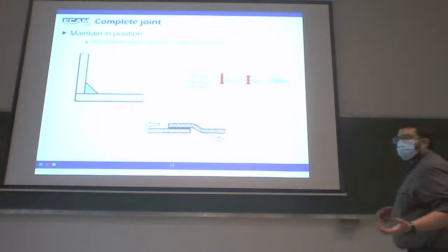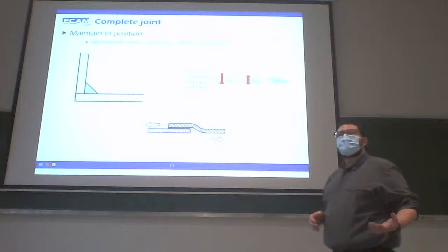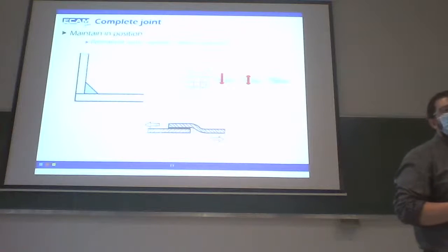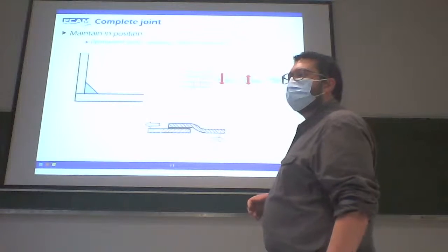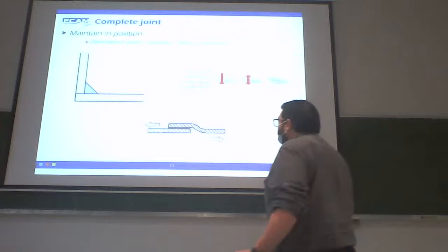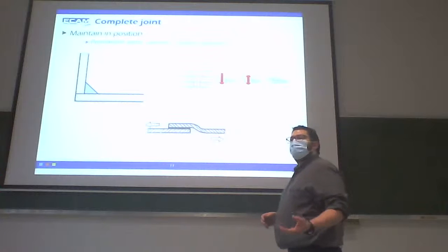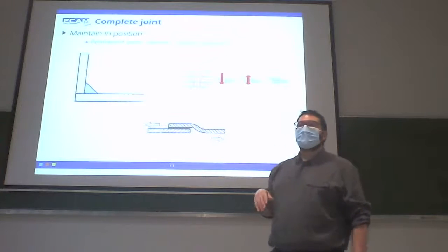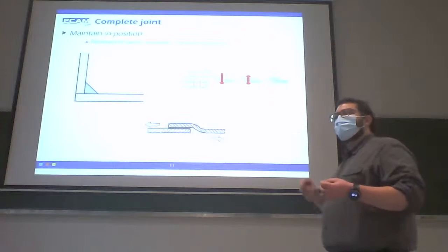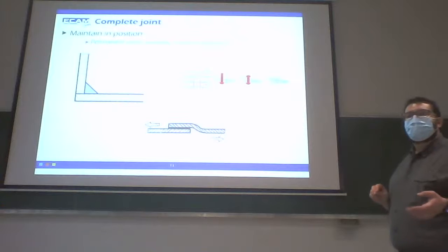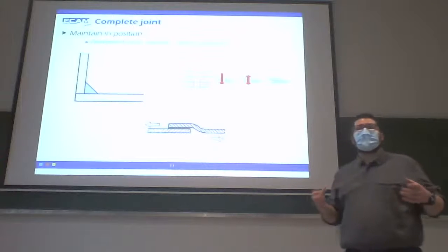Last solution, adhesion. We'll add an adhesion element, glue or something else, to fix two parts together. Adhesion is more and more used in industrial use. For example, 50 years ago, assembly of planes was by riveting. You see on the aluminum parts of a plane, you have all the small rivets. Now, between 50 to 60% of the parts of the external part of the plane are glued.